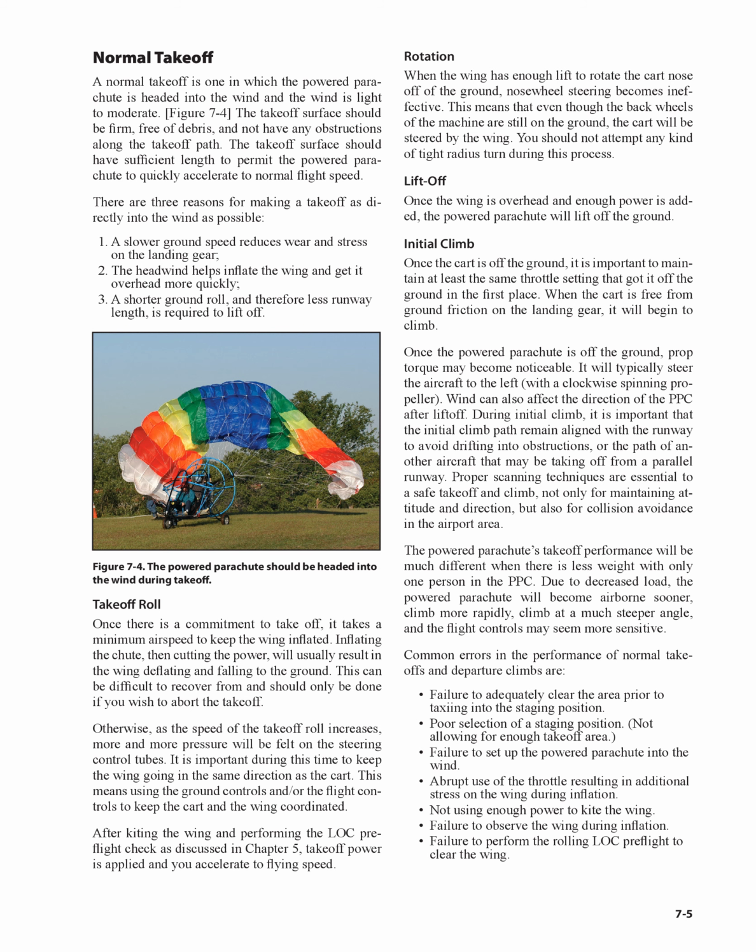During initial climb, it is important that the initial climb path remain aligned with the runway to avoid drifting into obstructions, or the path of another aircraft that may be taking off from a parallel runway. Proper scanning techniques are essential to a safe takeoff and climb, not only for maintaining attitude and direction, but also for collision avoidance in the airport area.